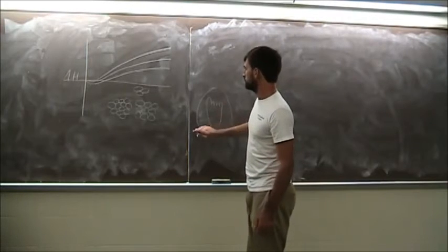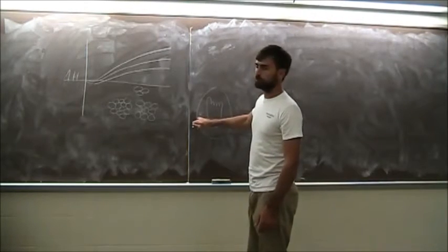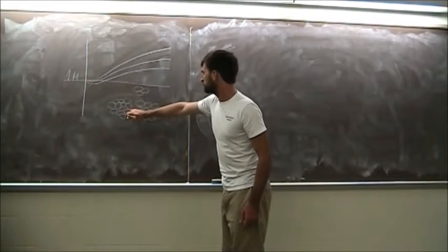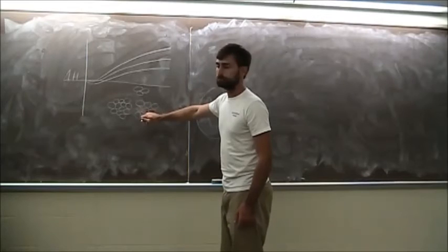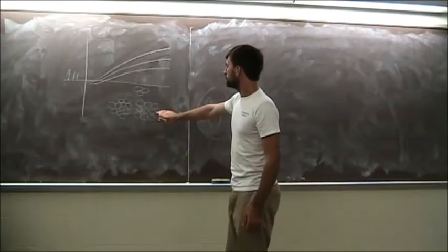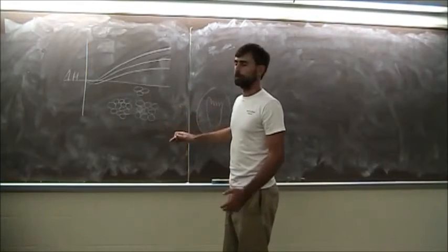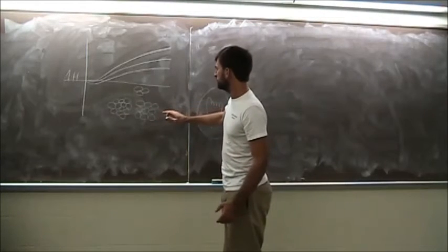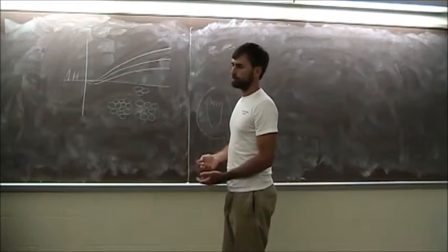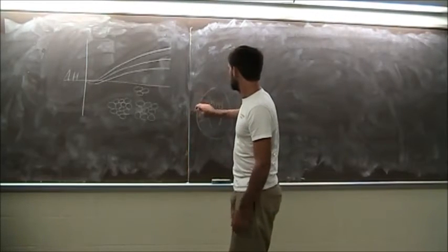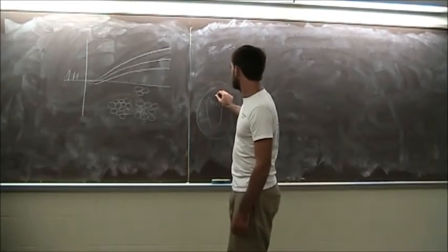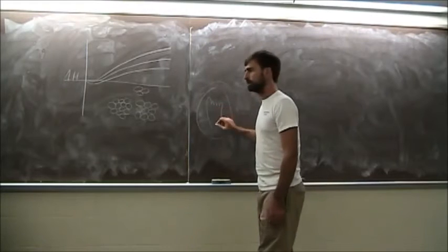What's happening here is when you step on that soil, you're shearing the soil around your foot. And you're moving from a dense configuration to a looser configuration, and since the particle volume can't change, you're increasing the pore volume, which means you're increasing the places for water to flow. So the water no longer sits on top of the sand surface like it is around here, and it soaks into the extra pore volume created by shearing the soil.